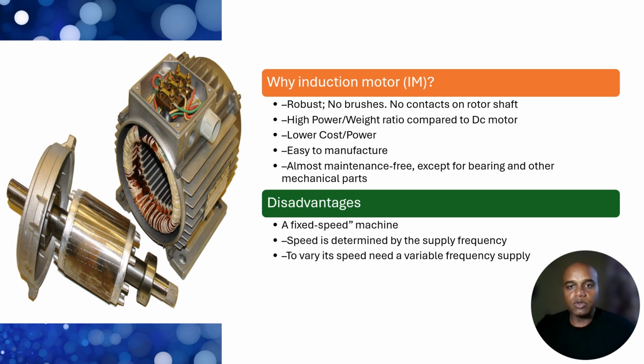What are the limitations? I would not say disadvantages. It employs a very complex speed control strategy, which is based on the supply frequency. So we have to vary the supply frequency to control the speed of the induction motor, which we will discuss thoroughly in another video. So it has some complex external circuitry for the speed control of a three-phase induction motor.